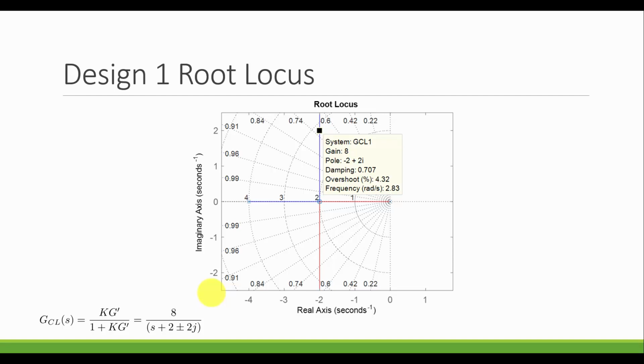So by choosing a zero in the compensator that was the same as an open loop pole, we actually get a closed loop transfer function that is a pure second order system. So when we go into the simulation, the theory and the simulation should match exactly because we don't have an extra zero or a third pole coming through and affecting the baseline system. The true system is the baseline system for this controller. So we know how in theory it's going to behave already from the previous lecture. So let's look at the simulation and just see how does it actually behave, at least in simulation numerically.